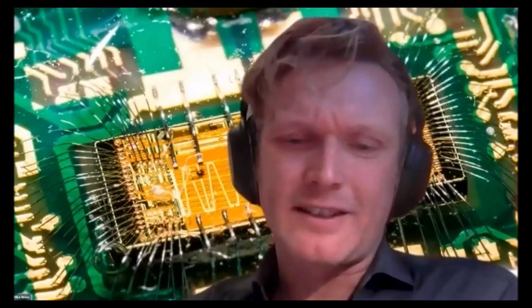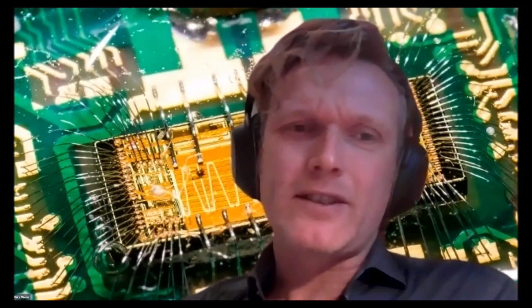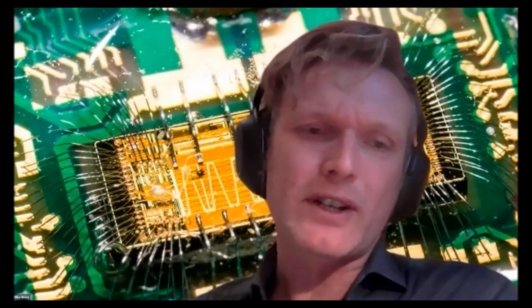I disagree here, Alex. From a user point of view, this really depends on 2 factors. First of all, you have to look at the devices available. They are what they are, so we have to deal with them. And second, you have to look at the voltage that you operate them at. If you're operating at, let's say, 100 volts, maybe up to 200 volts, you could do it without a negative voltage. But if you're operating at 400 volts and beyond, and 650, then the negative voltage is needed.